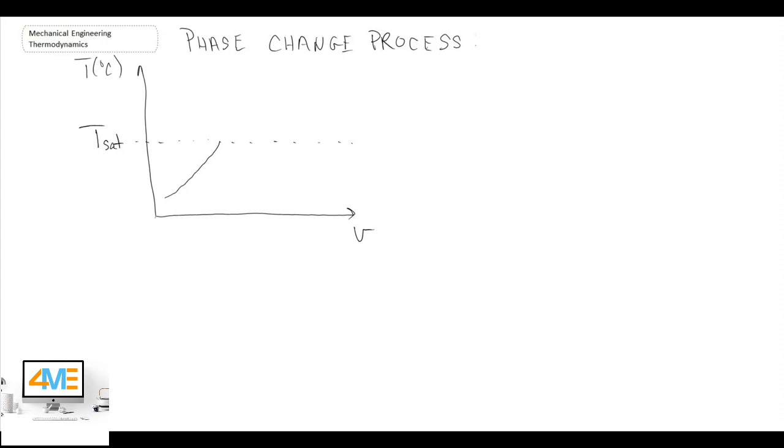So this is a line that's at a constant pressure that I've drawn here coming up to the saturation temperature. So what happens is we increase temperature, then we get to a point where we hit the saturation point, and that's when we're going through the phase change of boiling, and we refer to that as being a saturated mixture.